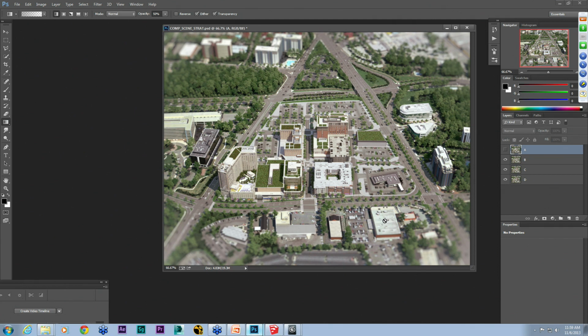And I know there's different functions in Max. You have the containers, you have XREFs, and then the actual XREF objects. We're very careful about what we choose to XREF, and it's generally a last resort because even with network rendering, we find we tend to get more bad frames or weird situations using XREFs, and we tend not to embed any plugins in XREFs.